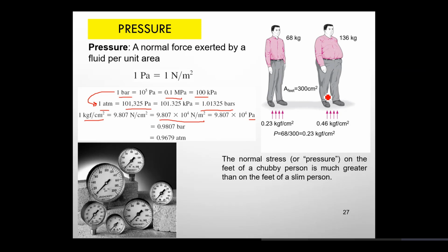If I go and buy a gauge which has a pressure range of 1 bar to, let's say, 200 bar, it would be very difficult for me to find where the 2 bar lies. Clear? Similarly, if the gauge is in PSI, you should be familiar with what range would be suitable for you. Clear? So the conversions become essential when you go to the market or when you're running experiments with gauges that are different from the experimental requirements. All right? All right. So what we'll do is that I'll stop over here.